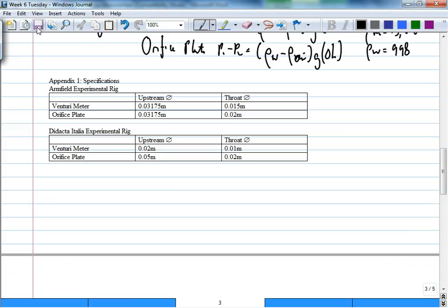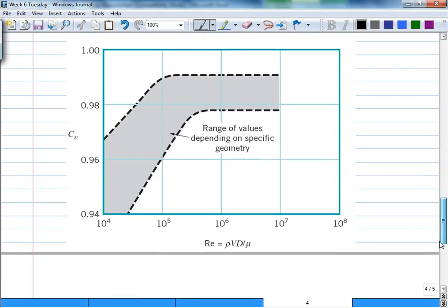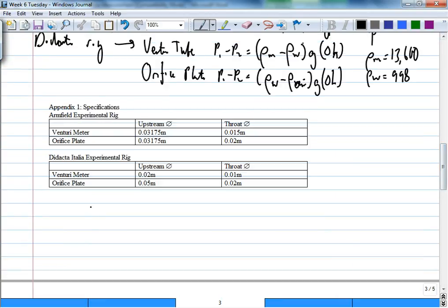And so for each case, you can work out a discharge coefficient. Well, they call it CV. Obviously I call it CQ, but anyway, same. Discharge coefficient is equal to Q actual over Q ideal. Is it the other way around? Actual less than ideal, should be less than 1. I think it's the first way. So you can work out a discharge coefficient.